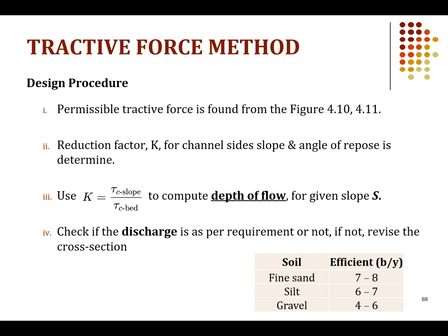Here is the design procedure for the tractive force method. The steps are listed here, and I shall directly go to solving the problem following these steps. The only thing I want to mention here is that in this problem we shall assume a ratio of bed width to the depth of the water. For different types of soil, you can appropriately choose these values.